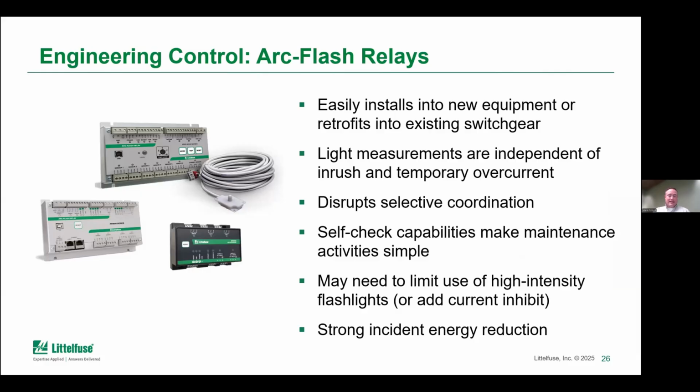One advantage is that it's independent of the inrush currents, so you don't have to worry about the settings and making sure your current settings are above those inrushes. But it does also disrupt that selective coordination, because now you're just tripping based on light, independent of what all the devices might be set for current.